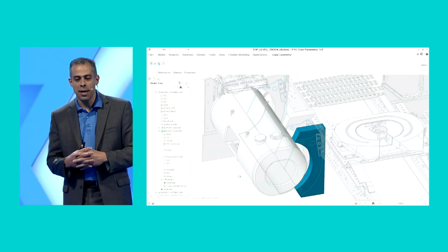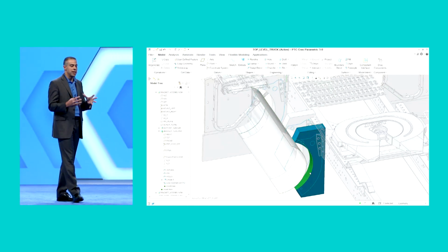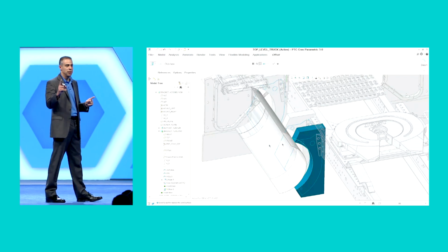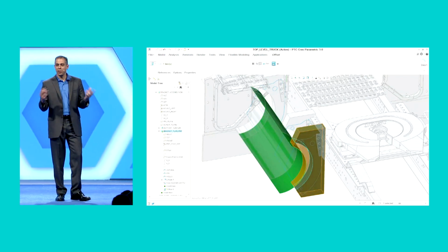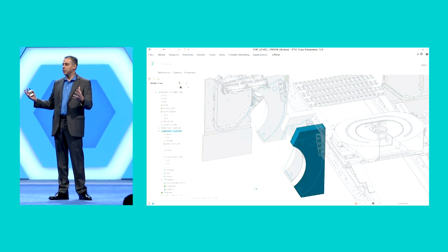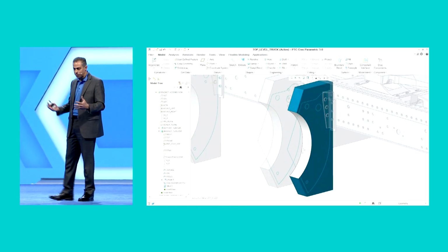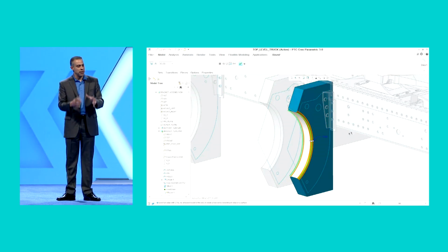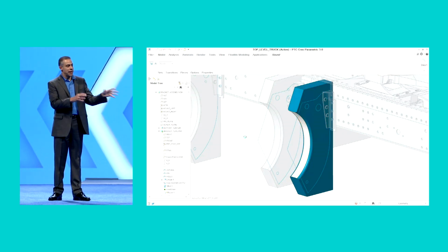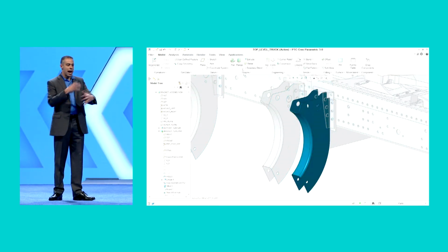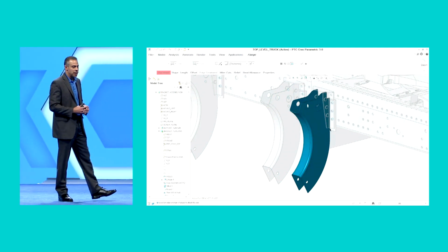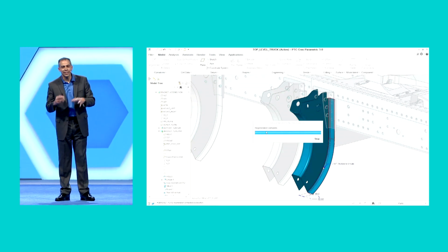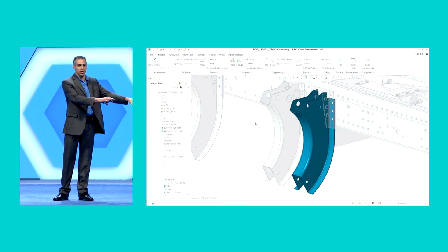Now what I'm going to do here is create an important relationship, a cross-platform relationship between the SolidWorks object and the Creo object. I'm going to use copy geom technology. This is technology you know and love, technology you've seen before. That copy geom technology gives me the opportunity of shaping my brackets to match the SolidWorks tank. So as I carry forward here, I've got a nice sheet metal object. I can carry forward with my design, finish that sheet metal object out, and start building downstream deliverables off of that object.